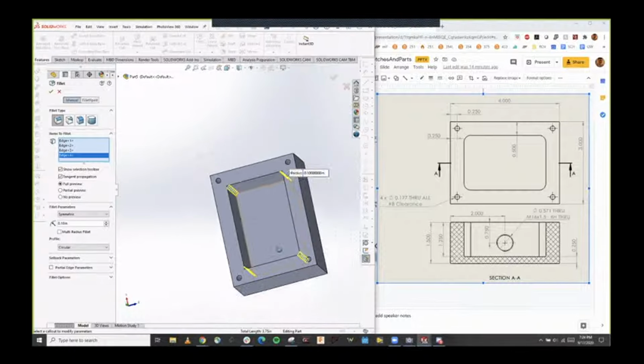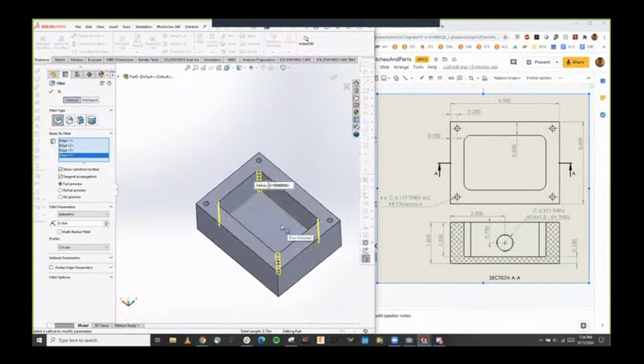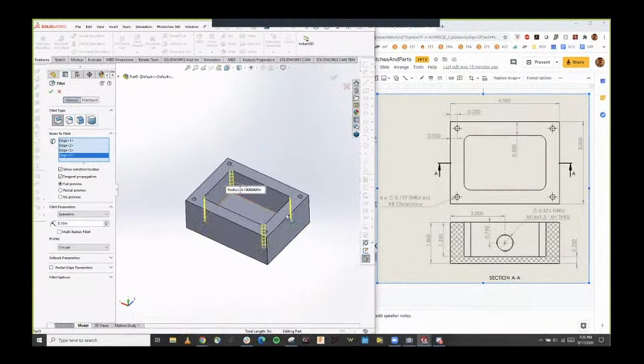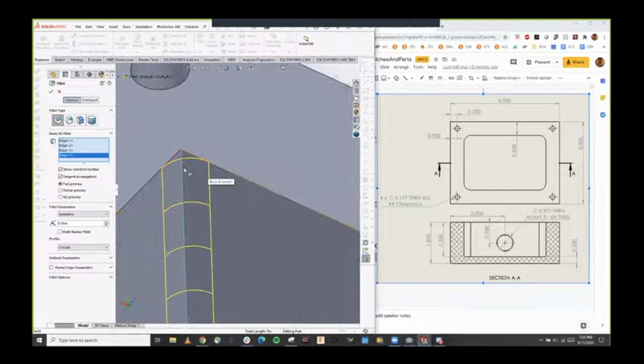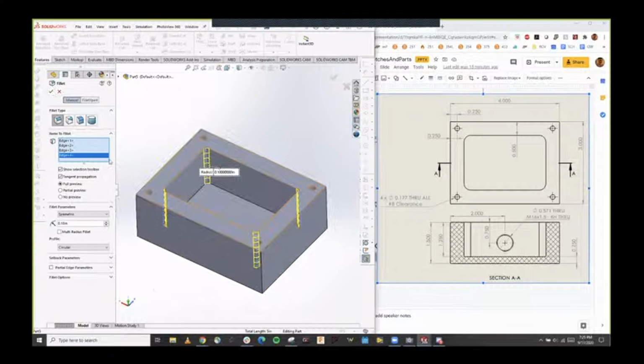So by creating these fillets, we actually make the part more resilient to failure and give it a higher yield strength. That's one of the other things in FEA. If we were to do part analysis, you would see these corners are where failure occurs first. I actually might be able to have an example of that. During the third CAD session, I'll show something we've been doing in machine design recently, ME354, which is an FEA analysis, just to show you what it looks like and to show why we don't leave corners unfilleted.